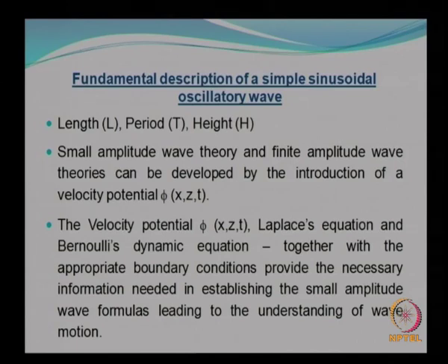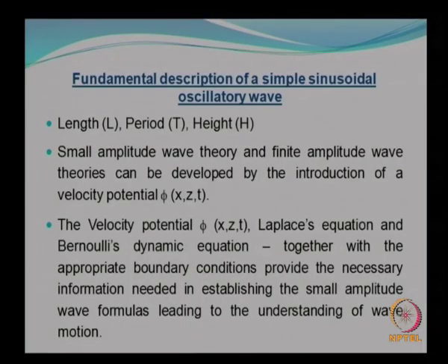The velocity potential can be obtained from a governing equation, and in this case the governing equation is nothing but the Laplace equation, del square phi is equal to 0. So, when you want to solve for the velocity potential from the governing Laplace equation, it has to naturally be subjected to certain boundary conditions, and herein we have few boundary conditions which we apply in order to derive the velocity potential.